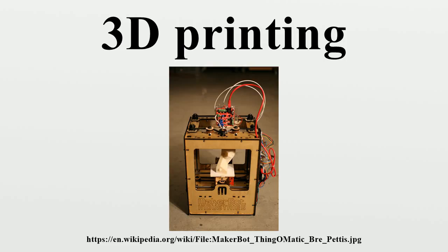Metal wire processors. Laser-based wire feed systems, such as laser metal deposition wire, feed wire through a nozzle that is melted by a laser using inert gas shielding in either an open environment or in a sealed chamber. Electron beam freeform fabrication uses an electron beam heat source inside a vacuum chamber.